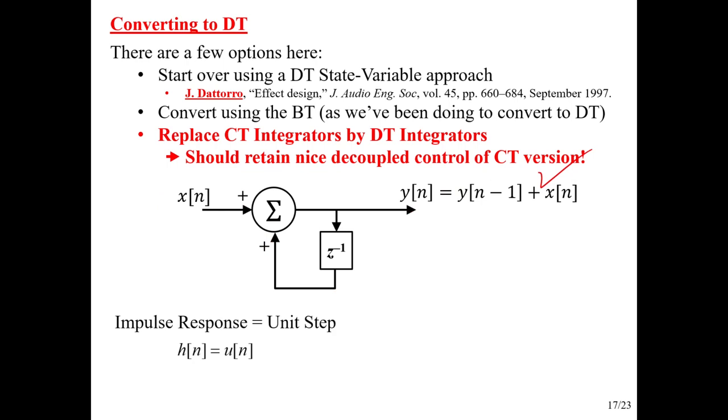So now let's put in an impulse response. If it really is an integrator, if you integrate a delta function in continuous time, you get a unit step. That might have been something you learned in a signals and systems class. If not, you can find that online. But it's pretty obvious. The area of a unit step is 1, and you're integrating along time.